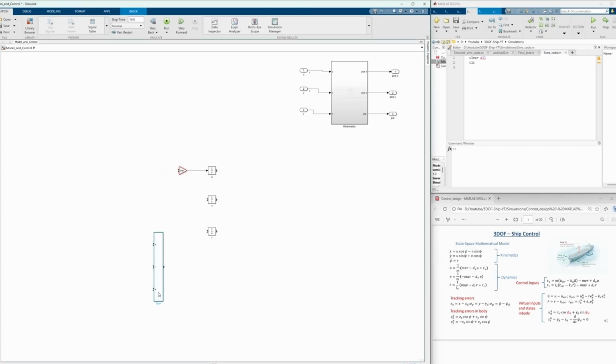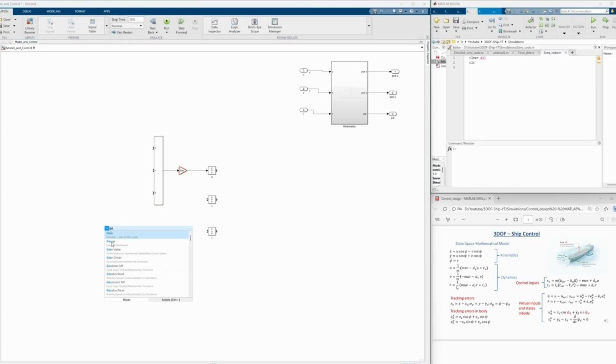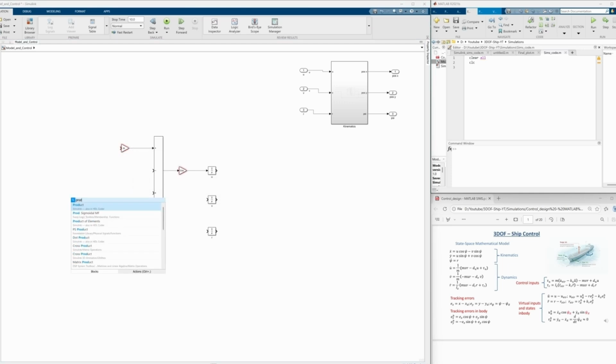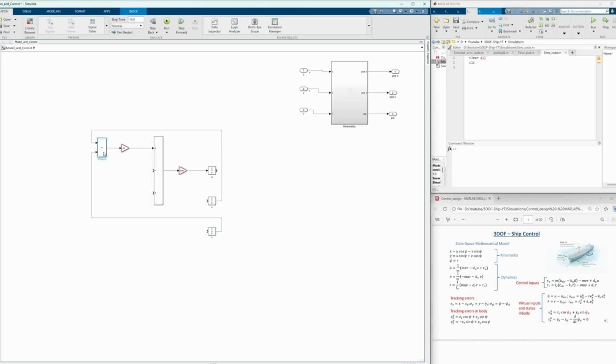And let me make it a bit bigger. So in the first one, we have an VR. So V and R are actually our states, and M is a constant. So for constant, I will add this because it is a multiplier, M. Okay, and then I need a product. So product here. So MVR, V, and this will connect it over here to R. Okay, if you remember, I told you to name these signals, so it becomes really helpful.